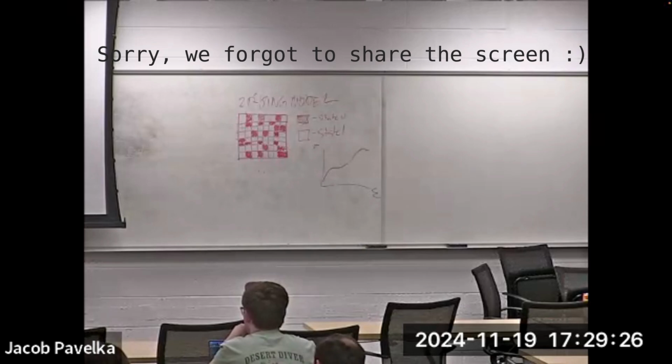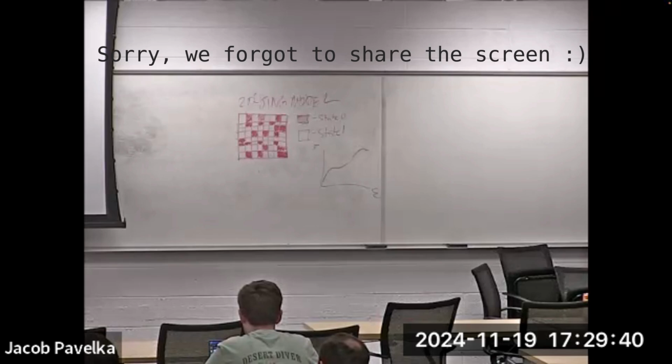We wouldn't expect that. Chaitali, I don't know what you think, because I tried many different things. I tried decreasing the element size. I tried very, very small time steps, and my residuals just plateau. No matter what I do, I tried 64 nonlinear increments, and it still levels off. I'm hesitant to say, but I think there may be some bug in the continuum plasticity codes. I think we have to look into that a bit more, just to see that much heterogeneity.